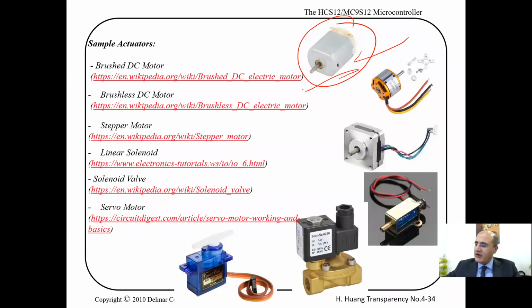If you see my camera, there are faster motors that are called brushless DC motors. A brushed DC motor has two lines, right? Two lines to provide the power. A brushless has three wires, and there is a brushless DC motor controller. It usually comes with a controller. How does it work? There are no brushes inside to internally reverse the voltage.